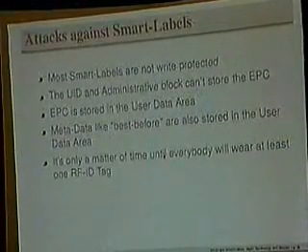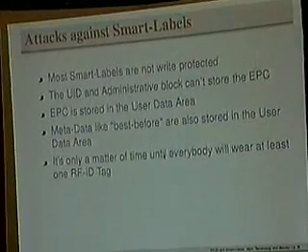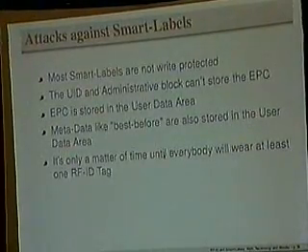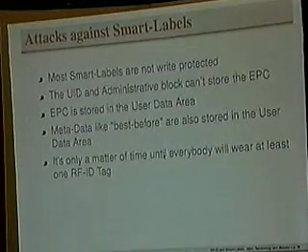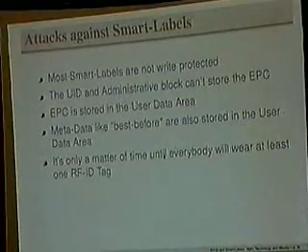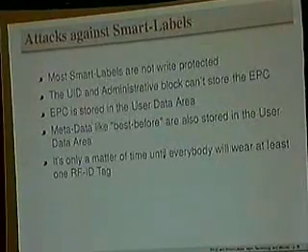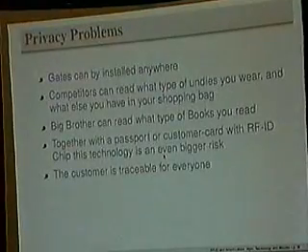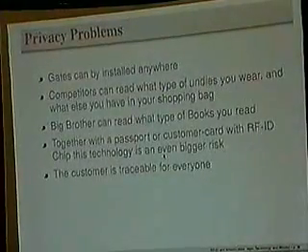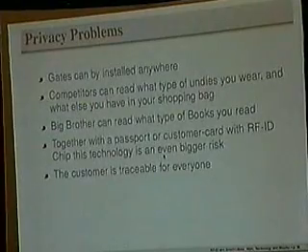Additionally, you have memory directly on this tag, and this memory is partitioned into two blocks. You have an administrative block. This administrative block holds the UID for the anti-collision and an application family identifier called AFI. Also a data storage format identifier, so if you don't know the format, you can read it directly from the administrative block. And you are able to store user data up to 128 bytes persistently.